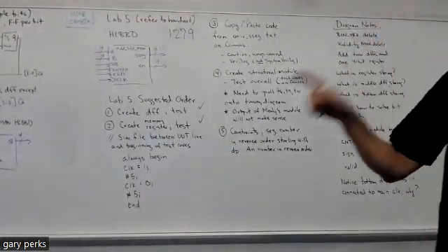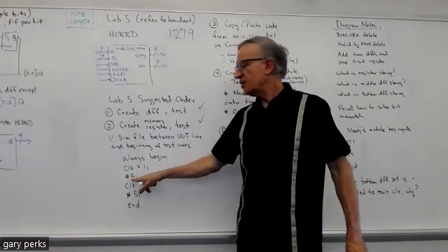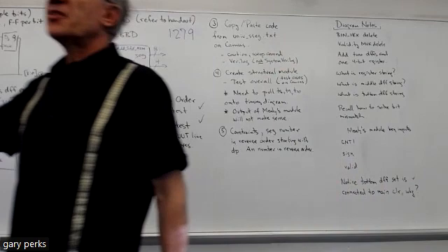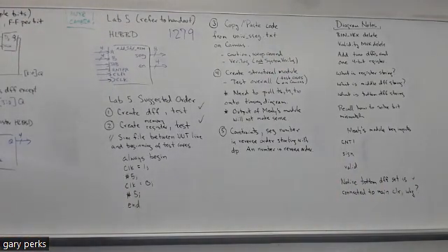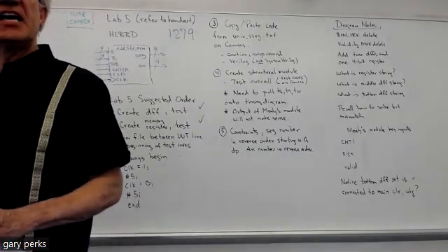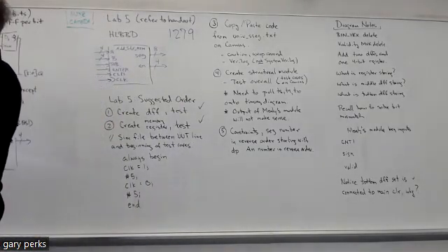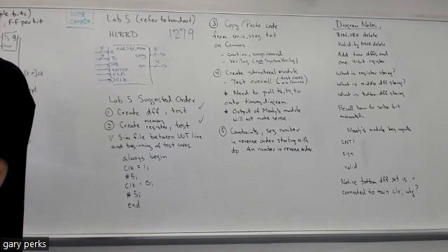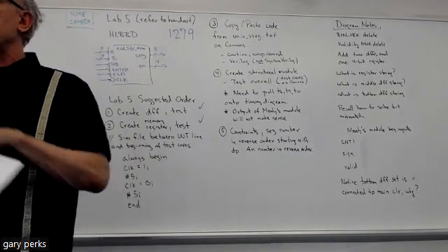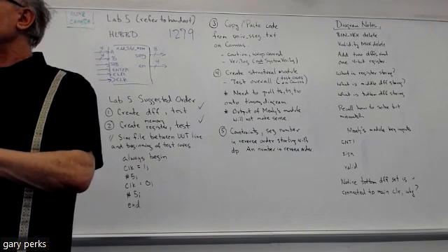Yeah, exactly. The number sign 10, the number that follows the number sign, tells you how many nanoseconds. So the reason you put number sign 10, then a test case, number sign 10, then a test case, and so on, is you're separating each test case by 10 nanoseconds. If you didn't have the number sign 10, then all your test cases on the timing diagram would be on top of each other. And it would just be unreadable, or probably wouldn't even run. Okay, so that's what the number sign 10 is doing. It's separating those test cases by 10 nanoseconds.